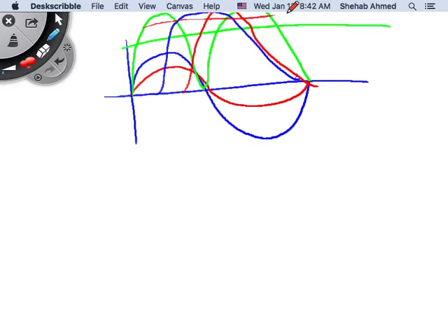But what is the value of current in all cases? The same. What's the value of voltage? In all cases, the same. So when you select a conductor and its insulation, do you select it based on power transfer, or do you select it based on voltage and current? Voltage and current, right? If you have two conductors next to each other, then you have to select the insulation to be a certain thickness so that you don't have arcing problems.